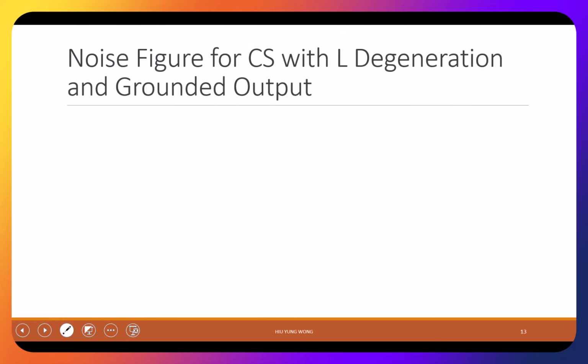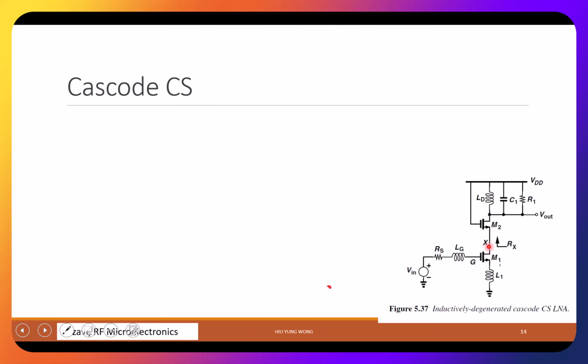So maybe I should show you what a Cascode circuit looks like first, right? So later I'm going to put this like this one, like what you did in your LNA, right? In your LNA, you look up, this is 1 over GM. 1 over GM is small, right? If you want, you can put 1 over GM as the load, but it's complicated. It makes the calculation complicated, right? So we say just approximate it as grounded.